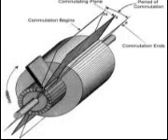A practical DC generator uses electromagnets instead of permanent magnets. To produce a magnetic field of the necessary strength with permanent magnets would greatly increase the physical size of the generator. The field coils are made up of many turns of insulated wire and are usually wound on a form which fits over the iron core of the pole to which it is securely fastened, figure 9-11. The exciting current, which is used to produce the magnetic field and which flows through the field coils, is obtained from an external source or from the generated DC of the machine.